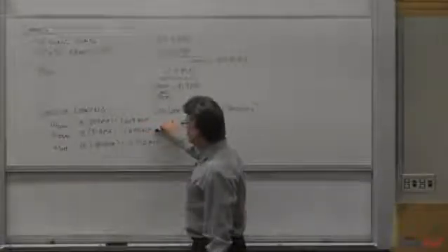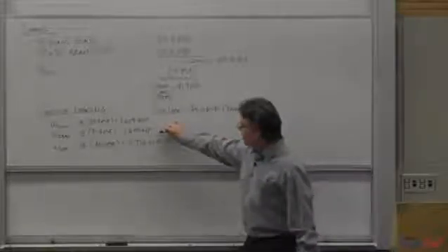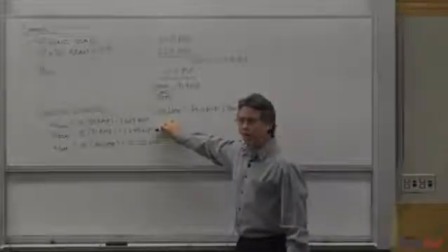1.609 kips per foot. The dead load in the system is 1.645 kips per foot. All I've done is calculated the line load on this beam. The live load is 0.72 kips per foot.